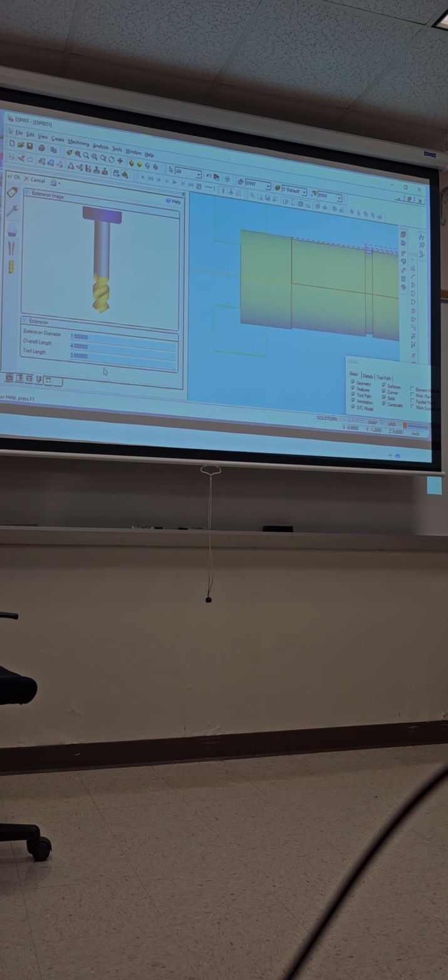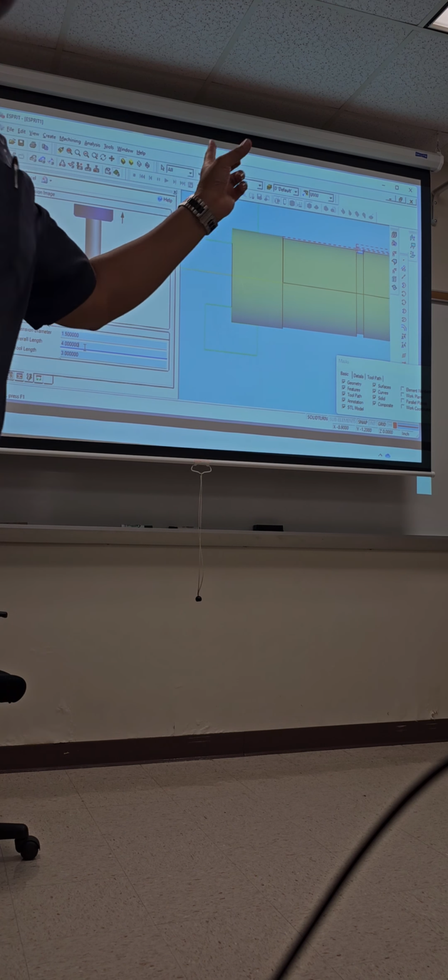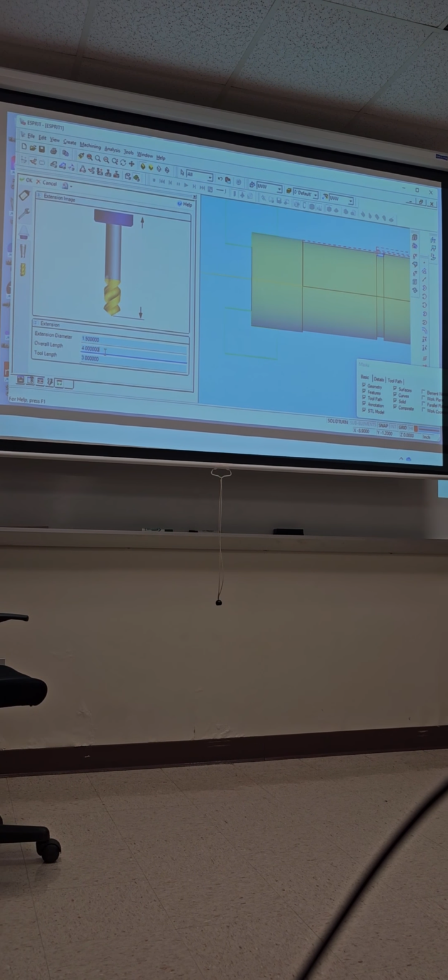Okay, so now we need a 1 inch overall Z length. Plus, you want to go negative? So remember, Corey, because we're stealing a tool from the mill, it doesn't make sense on the lathe. So you need to remember that, okay? So we're gonna drill it back 5 inches. So at least we need to have a clearance of 6 inches, right? So overall length, let's put it at 7, and tool length, let's put it at 6 because we need 5.